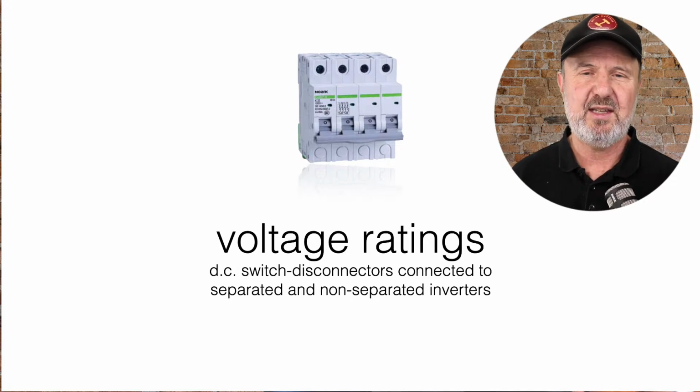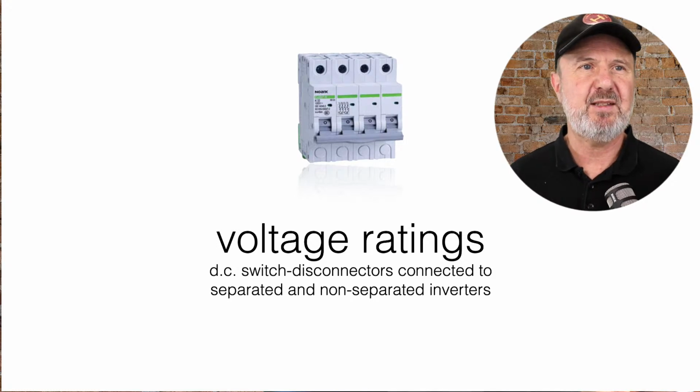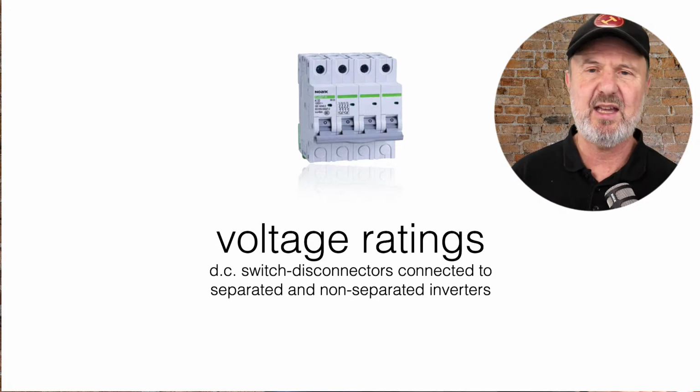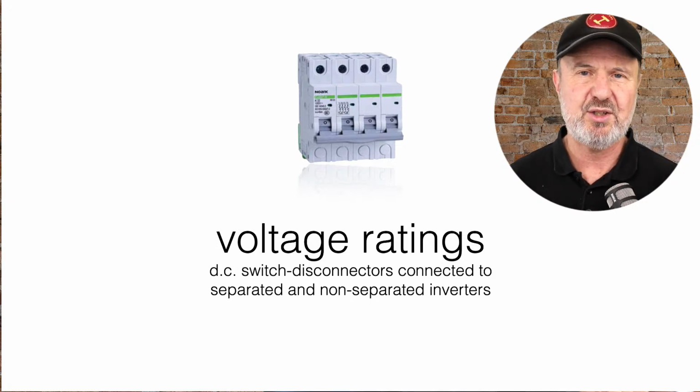Now, the thing that newcomers to this industry find surprising is that there isn't actually a standard voltage for switchgear. You might be used to going to a wholesaler and buying a 6 kA circuit breaker for a domestic application, or a 10 kA for a commercial, but you just know that the voltages are what they are. They're the grid voltages, so you don't actually have to specify a voltage rating for your switchgear or your cable protection equipment.